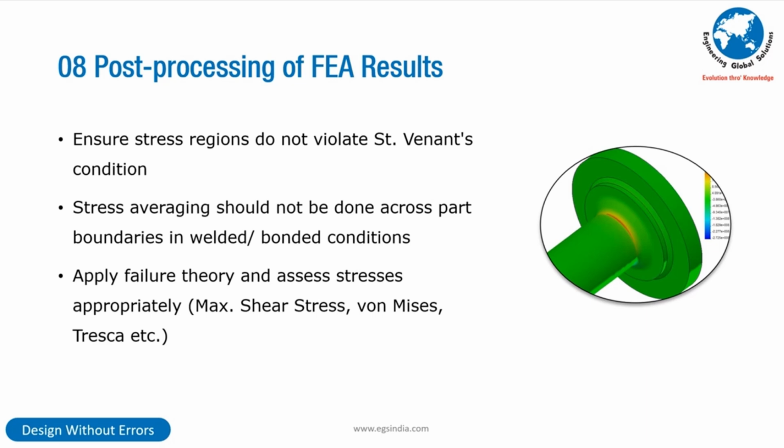What you're seeing on the right is actually a German design, where the design failed miserably. He had given a warranty of 10 years and it started failing in the third year. I happened to be there at the customer place and I said, this was a classic case of factor of safety design versus life-based designs. You know what he said? We Germans do factor of safety designs. He said that proudly. I said, well, start doing life-based designs, otherwise pay warranty costs. This is a classic failure.